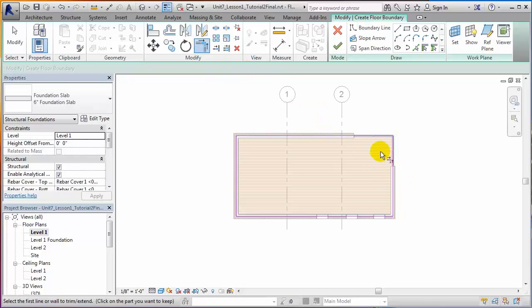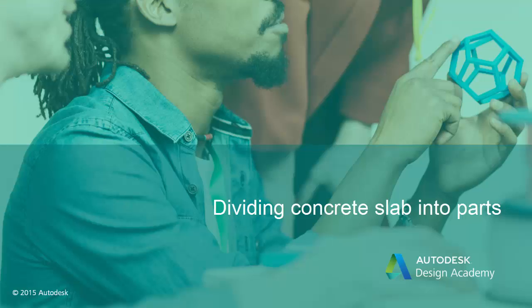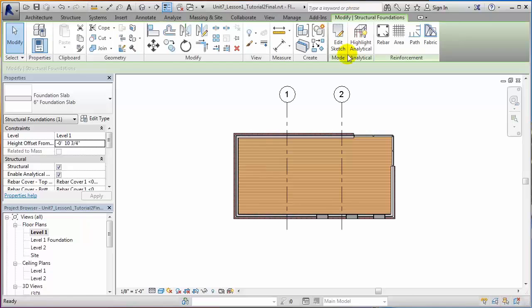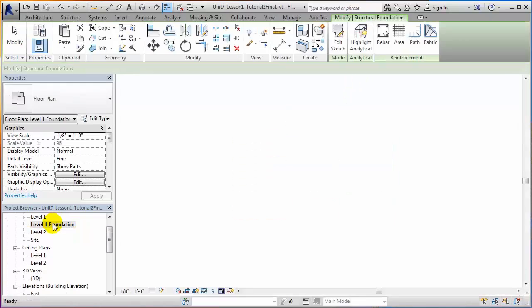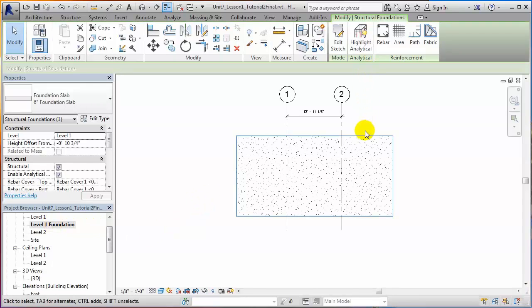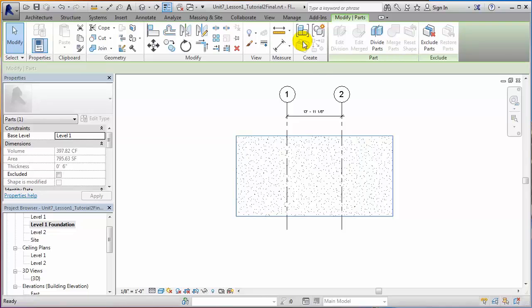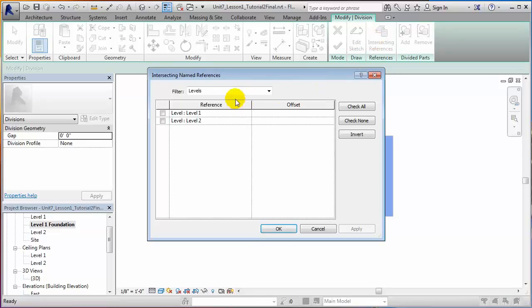I'm going to adjust the level so that it appears just below the floor, and I'll accept that. In this special view, where I've isolated the foundation, I'm going to sketch the parts division, which will allow the material division. I'll leverage my grid lines since they match my basement division program. We'll choose both grids since they will be needed for the concrete pour sequences anyway.